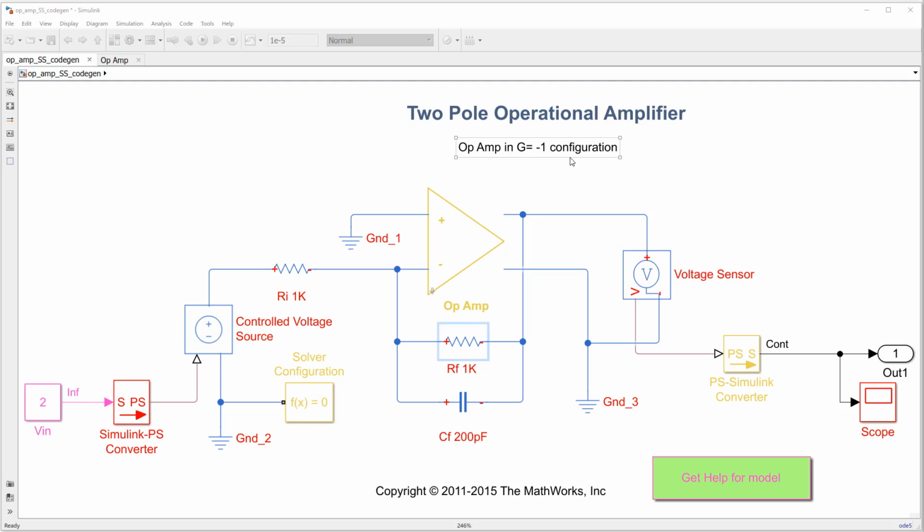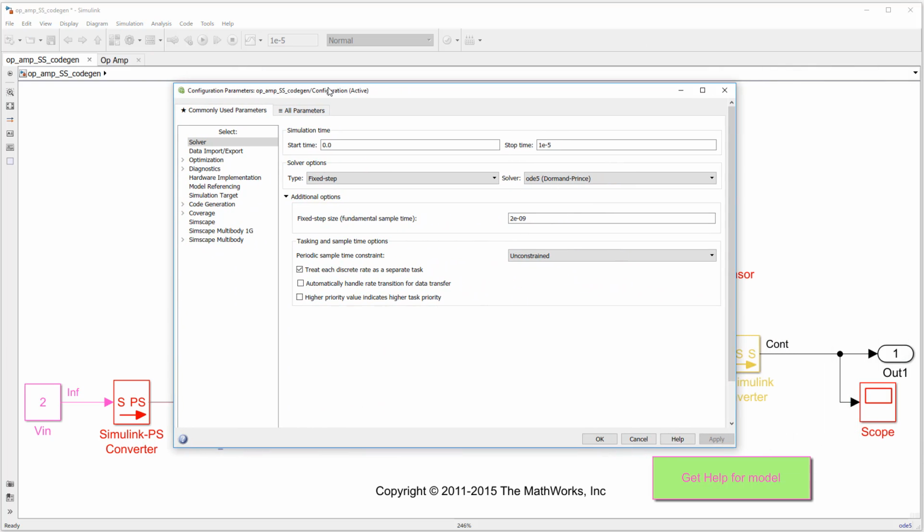In order to do this, we use code generation and export the model into a format that DMI can understand. The tool required from MathWorks to do this is our Embedded Coder. Embedded Coder allows us to customize ANSI C code for a particular target or application. In this case, we will customize C code for PSpice DMI.